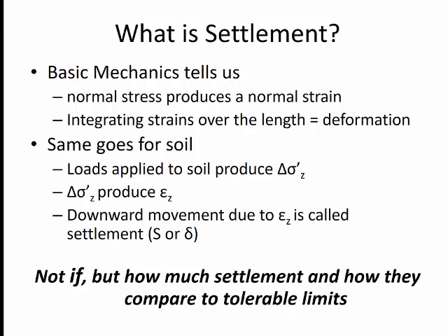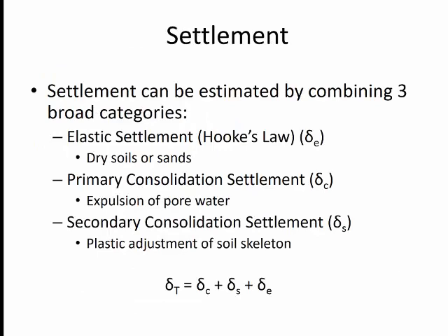And that is the downward movement of soil as stresses or loads are applied at the surface or some location. And so what I like to tell students is it's not a matter of if settlement will occur, it's how much, and can those settlements be confined to tolerable limits that are placed on that site or for that structure. I also add, and we'll see this later, is how much time will it take as well, because that is another aspect that we often need to utilize and understand when we look at calculating settlement.